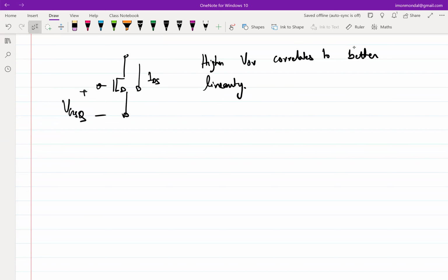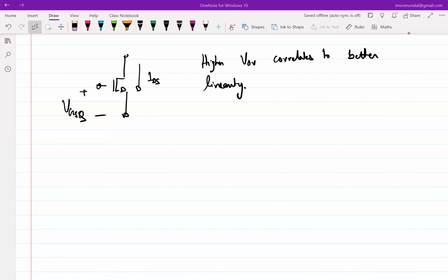The reason it is difficult to show any order nonlinearity in this context is because the very simplistic square law model that we take for the MOSFET does not, by definition, allow you to go to higher harmonics, right? So if you want to see the effect of higher harmonics, you obviously have to use some other model of the transistor.